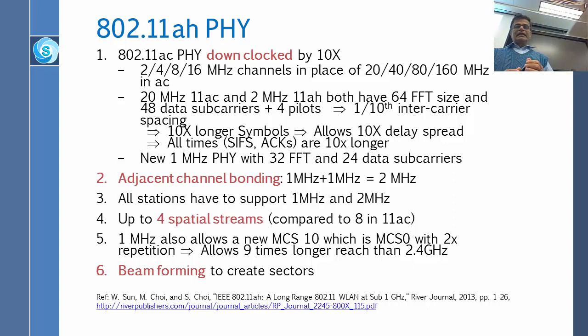Okay. Now, when you put things closer together, two things happen. First of all, the carriers are very close, so there could be inter-carrier interference. Right? That's why you don't want to put them too close. But there is the opposite effect too, and that is the duration of the symbol. Remember, FFT T is 1 upon F. If you remember, those of you at least who took the second exam probably remember it much better than those who didn't. So T is 1 upon F, so the symbol duration is large, 10 times basically.